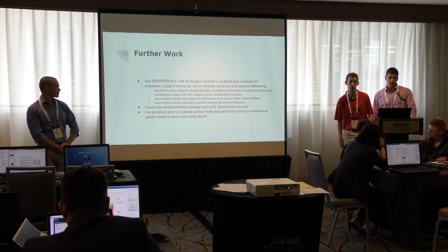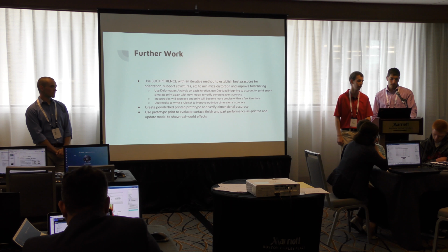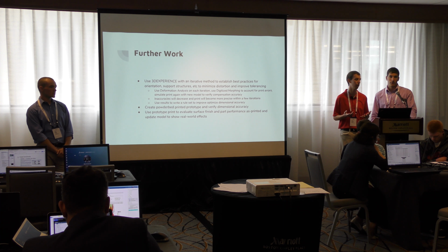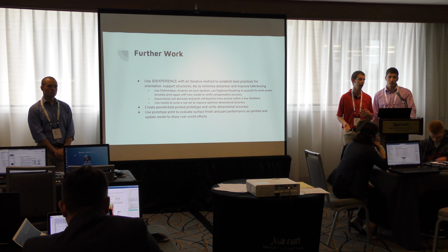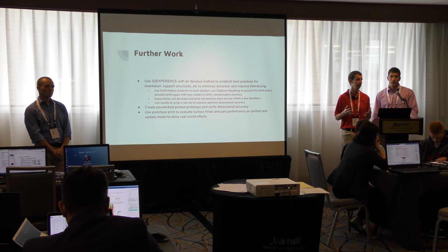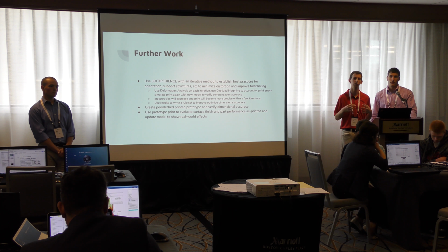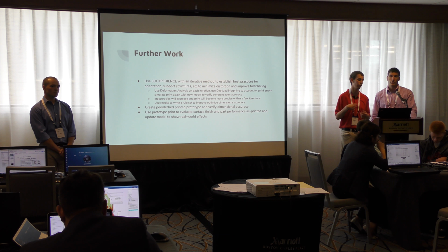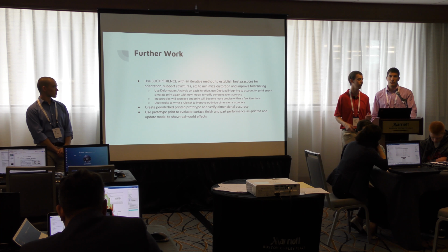Okay, so further work that we would like to do with this project, if we were given the time, would be first to take the resulting models, so the deformed models, and then we already use tools within 3D Experience to basically perform a -1 gain on that displacement, and then create 3D models of what we expect the model should be in order to print and reverse that deformation, so that the same deformation ends up creating a very tightly toleranced part according to the original CAD model.